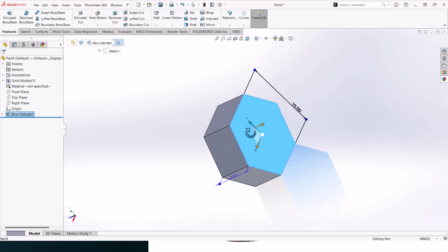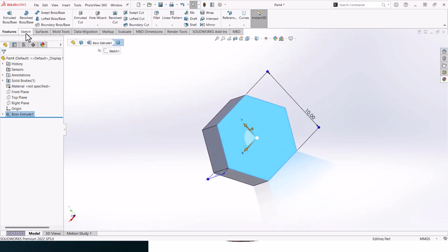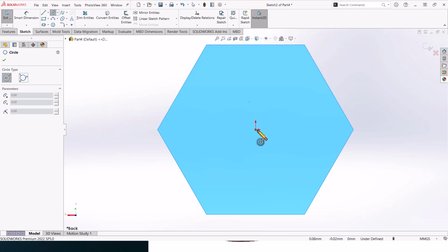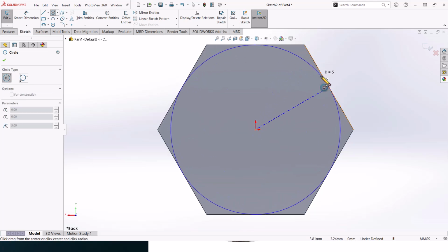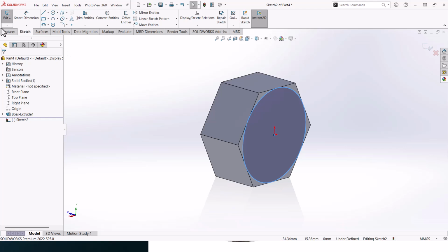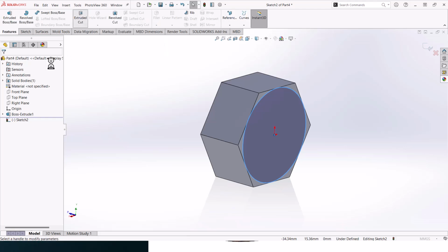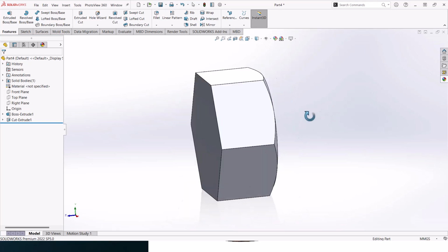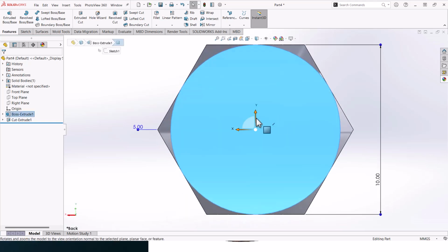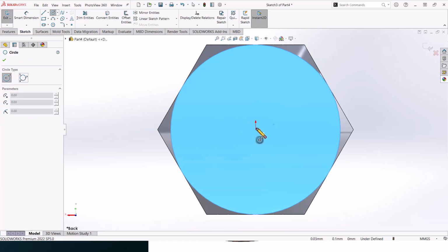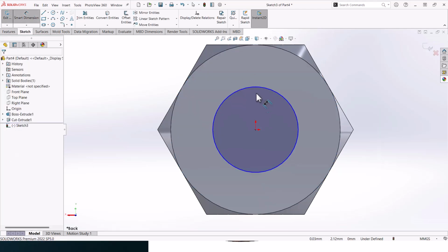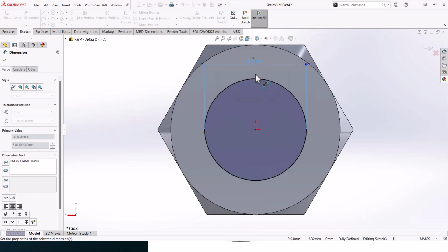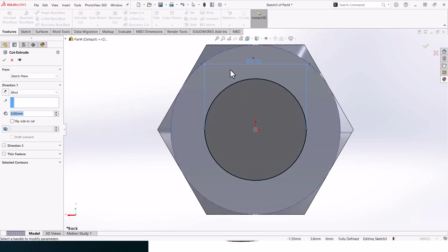Alright. Now let's again create chamfers. One on the top, right here, should be tangent, good. And then feature, extruded cut, sweep, flip side, good. Should be like that. Now let's create a hole in the middle. It should be 6 millimeters. Enter, good. Extruded cut, through all, good.